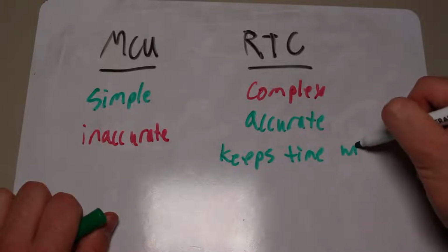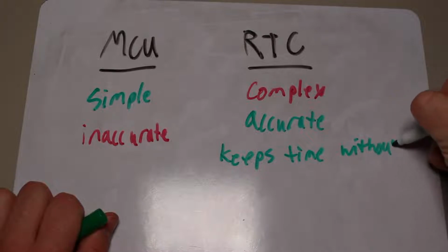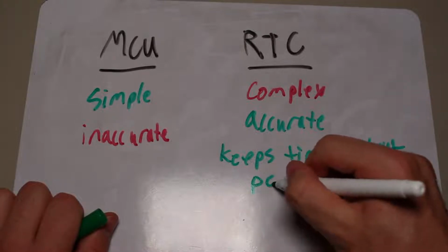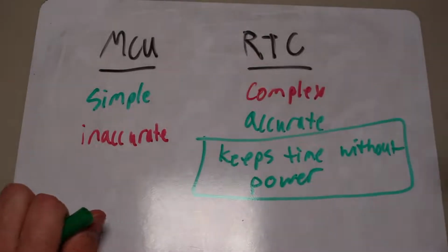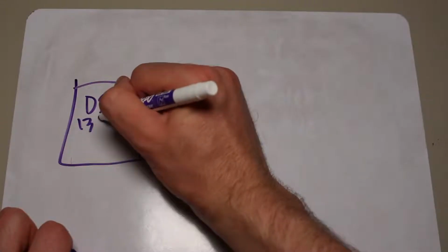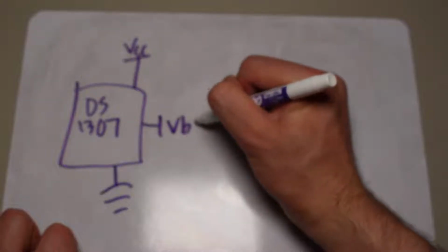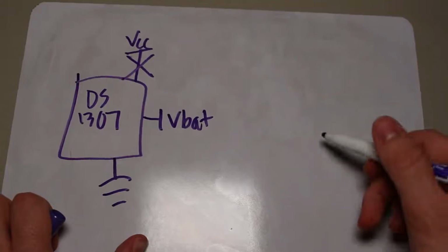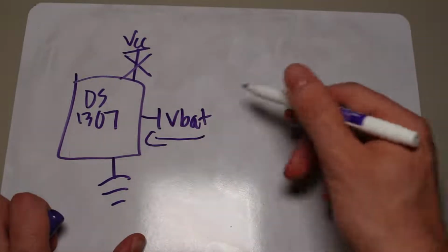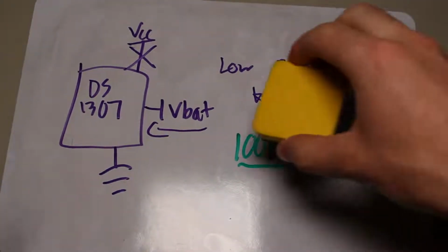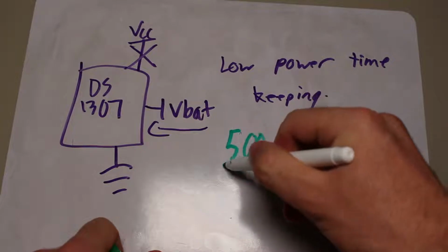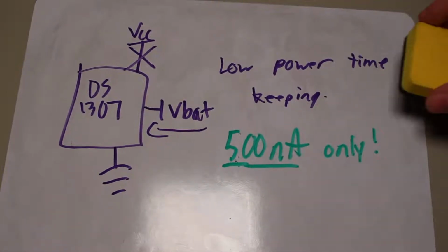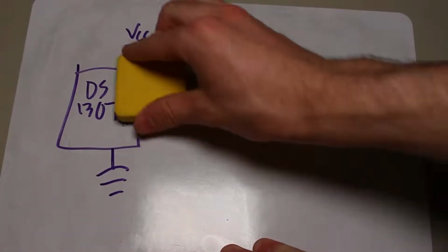However, the RTC isn't 100% accurate either, but it is close enough to function as a usable timer with adjustment every few months. It also features the use of a small battery to power it in the case of power loss. That means if your power goes out, it will still keep track of time so that you don't have to reset it when the power is restored. In the battery mode, it uses a measly 500 nanoamps of current, meaning that you can run it in this mode for several years. Now, we need to pick the microcontroller and output method.